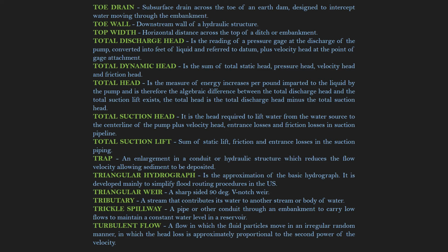Total suction head. It is the head required to lift water from the water source to the center line of the pump plus velocity head, entrance losses and friction losses in the suction pipeline. Total suction lift. Sum of static lift, friction and entrance losses in the suction piping.